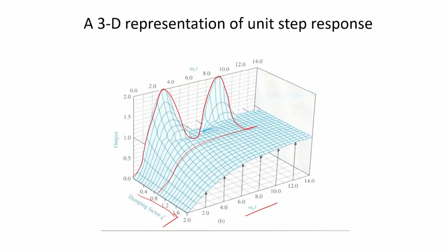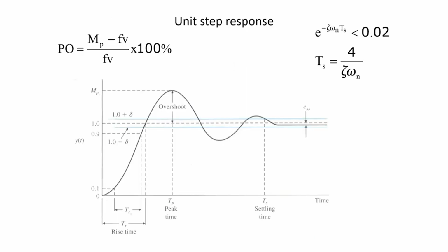Now, what is important for us is that take any such time slice and then you have to define some basic 5 specifications of the system. In all, I will talk about 7 specifications, but 5 we can define through these unit step response of the system itself. What are these 5? First one is the rise time. That means, if unit step is my desired reference, then the first time required to first reach your signal to this point, is called the rise time.